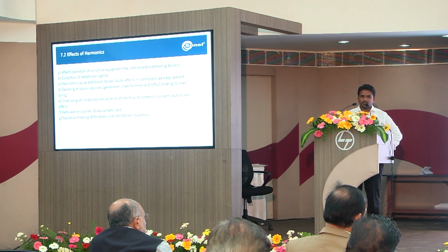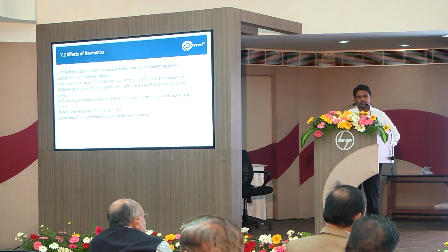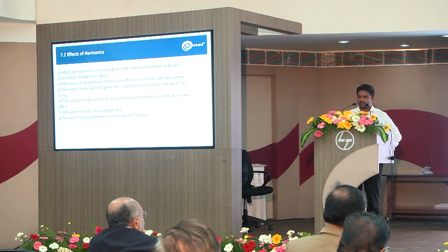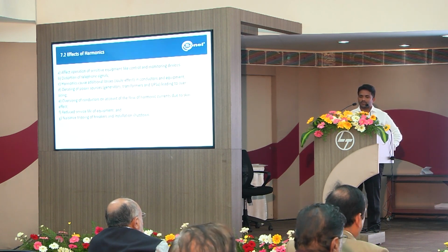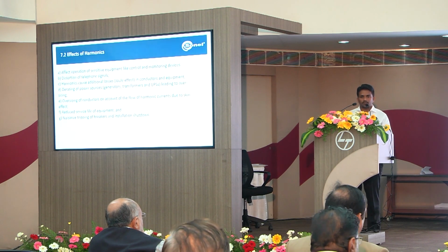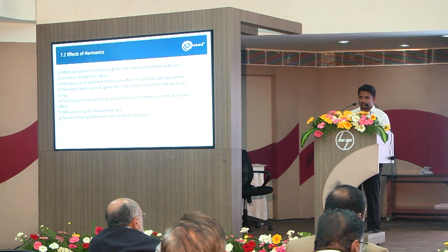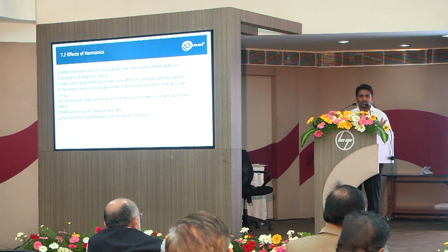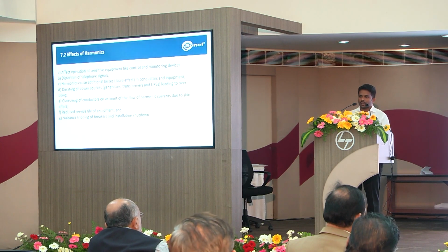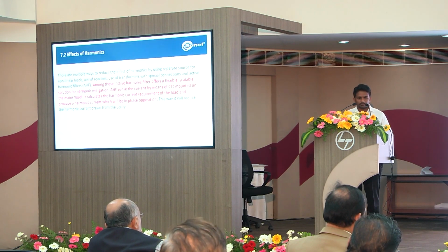But today in India, when we talk about power quality, even if we discuss a lot of parameters such as voltage sag, swell and other parameters, when it comes to the economics of power quality, we are all very curious about what is the measurement of power factor and how is our harmonic current being limited.